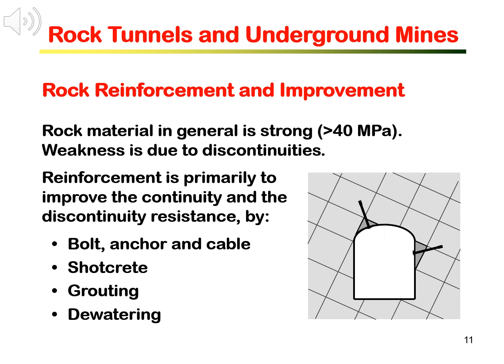For competent and reasonably good rock mass, rock material strength is generally higher than concrete. Failures of rock tunnels and caverns are mainly due to the joints and the fractures in the rock mass. Therefore, rock reinforcement is aiming to improve the rock mass to become continuous or to have higher resistance of the joints and the fractures